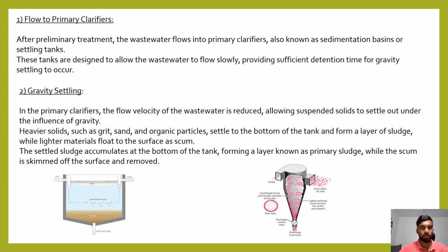After preliminary treatment, the wastewater flows into primary clarifiers, also known as sedimentation basins or settling tanks. These tanks are designed to allow wastewater to flow slowly, providing sufficient detention time for gravity settling to occur. Second one is gravity settling.